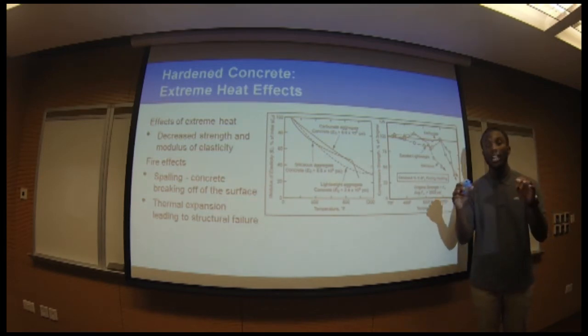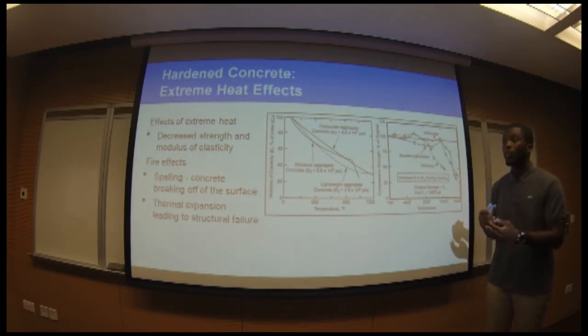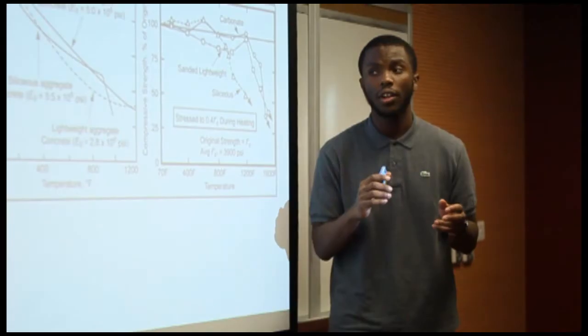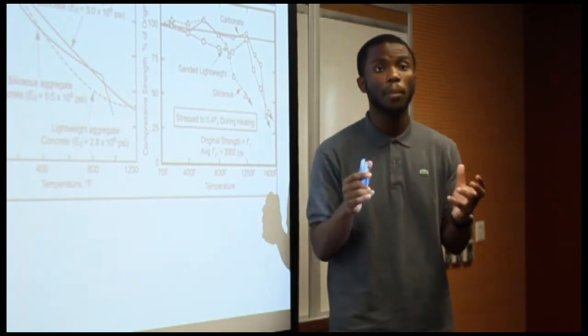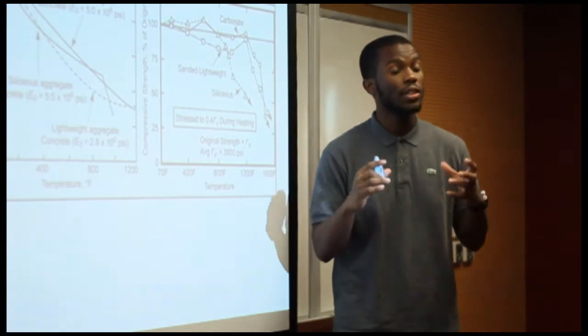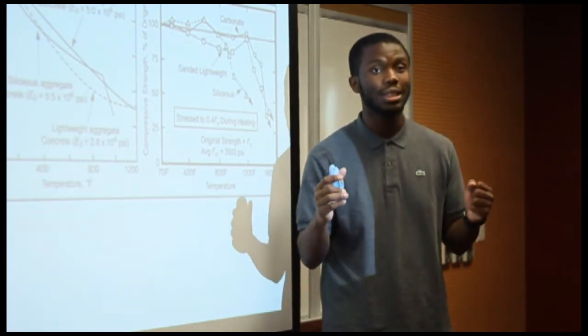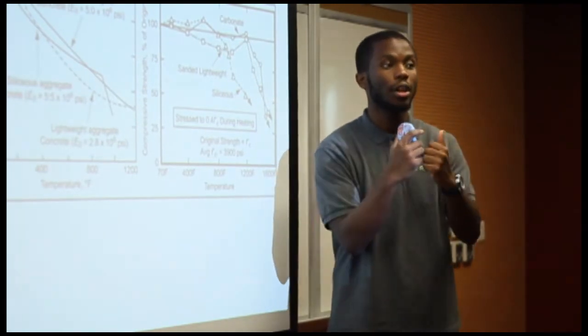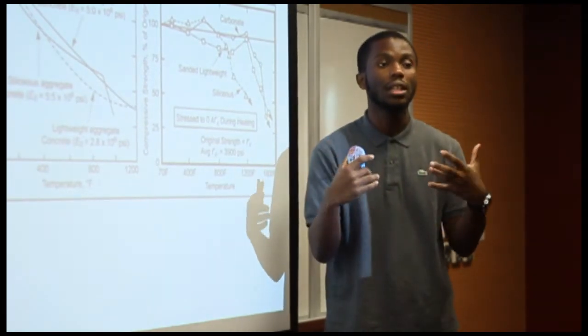Thermal expansion is one last part, which is very important since this is what leads to structural failure. Because concrete does not actually burn, but instead, when it expands, that steel, if it's a reinforced concrete, also expands, and that's where you have joint mishaps and of course the pressures building up and things collapsing and structural failure.